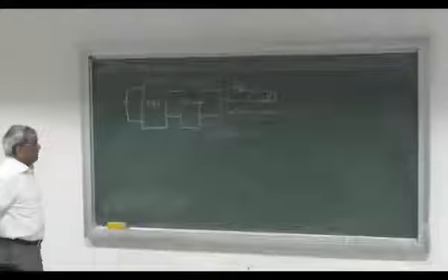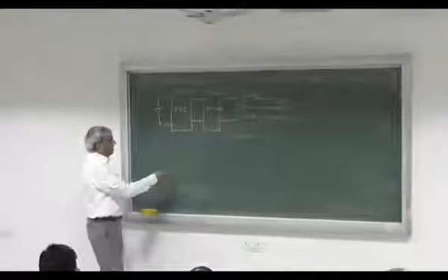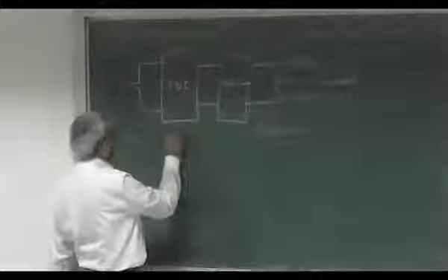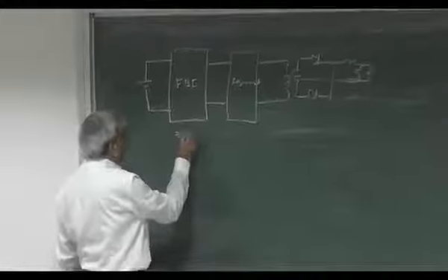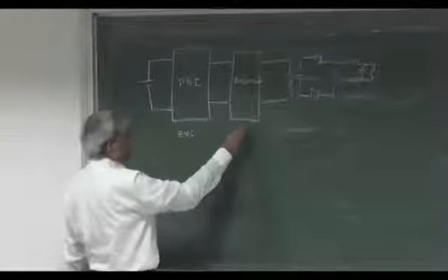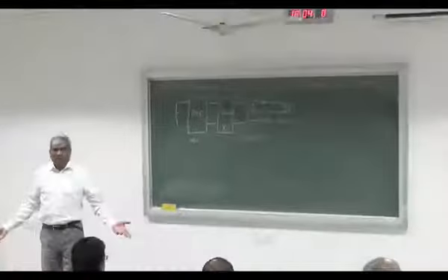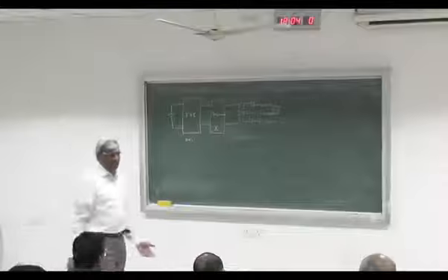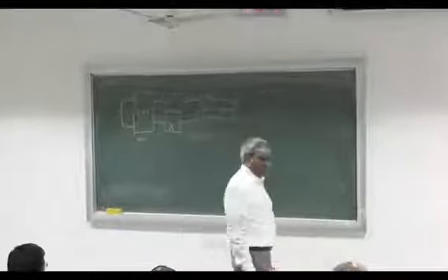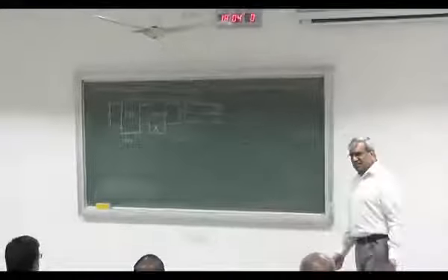We have this one, right? So if we can achieve the zero voltage switching here for this full bridge inverter without a resonant circuit, and that's what we saw, right? We can achieve the soft switching or zero voltage switching without the resonant circuit.